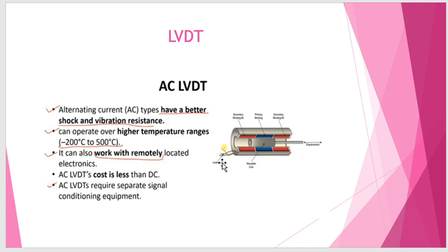That is because in an LVDT there are some output signals that are tricky, similar to the DC LVDT, where you have an AC power input but the output is DC. You can see that the signal conditioning equipment is built into the LVDT. Basically it all looks the same as this LVDT, but the output goes to an electronic circuit for signal conditioning.